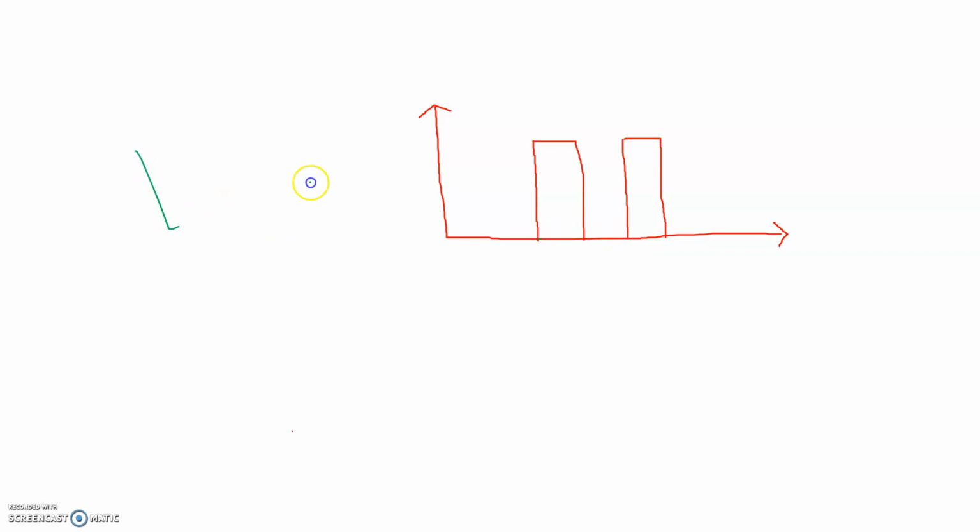I told you that the charging curve goes like this and the discharging curve goes like this. The capacitor will start charging initially, but it cannot charge up to VCC. Suppose this voltage is VCC, in our discussion it may be 1 volt or 5 volt, whatever, according to your adjustment in the signal generator.